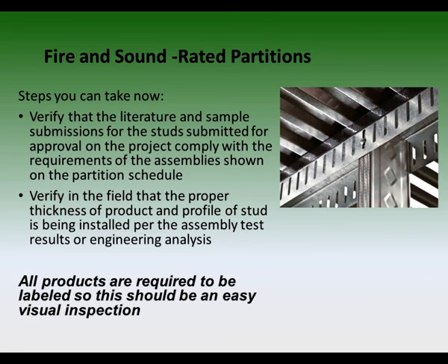The bottom line is verify. Compare literature and submissions with the plans or partition schedules, and compare field members to the approved assembly requirements. Given that all products are required to be labeled, this is not a difficult task for EQ or other code-compliant studs.